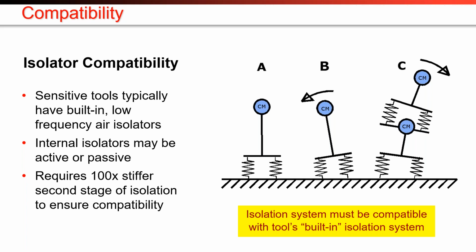If you have an order of magnitude amplification of the upper spring and an order of magnitude amplification at the lower spring, and they're at about the same frequency, say 2 hertz, now you've got 2 orders of magnitude amplification, which is a problem. The other problem, of course, is just stability issues. Stacking low frequency springs, just the basic physics starts causing you problems.